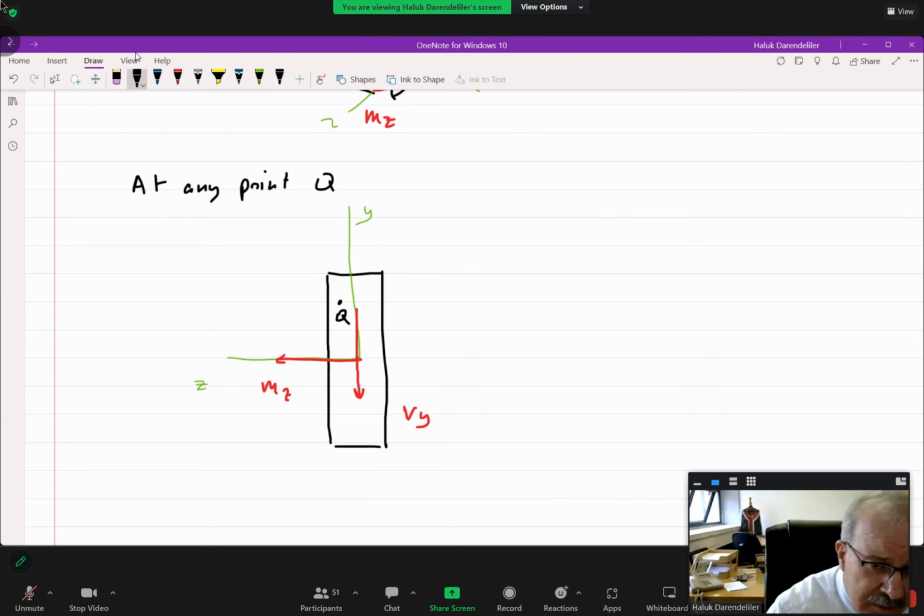Look carefully here. I know that this is also the neutral axis of the cross section. I am looking for the Q. Now, if possible, because I'm going to change this later, draw a line parallel to the neutral axis, passing through Q and dividing the shape into two.